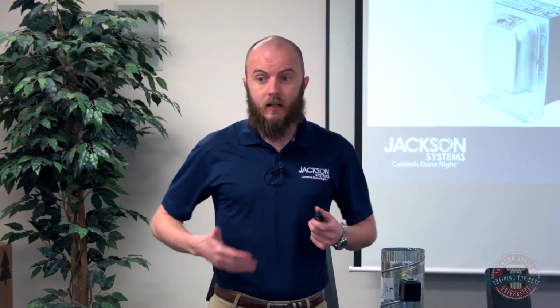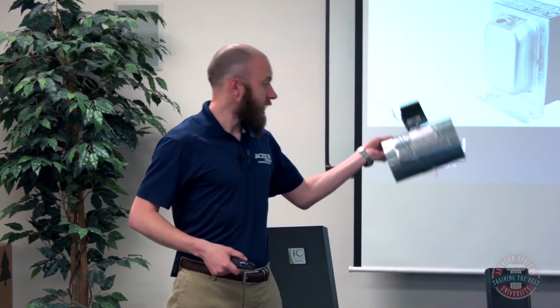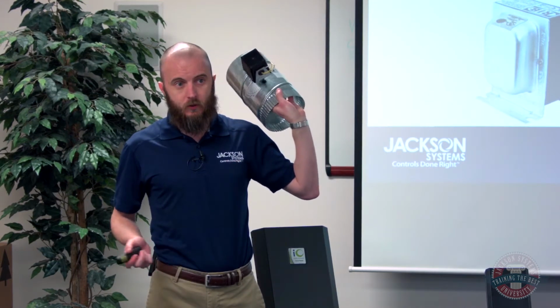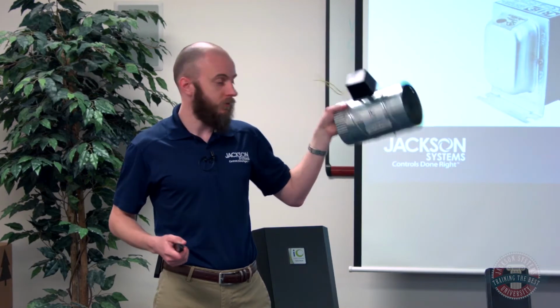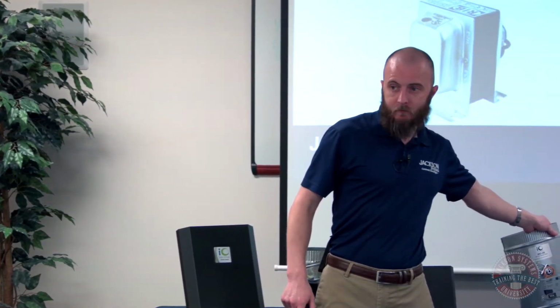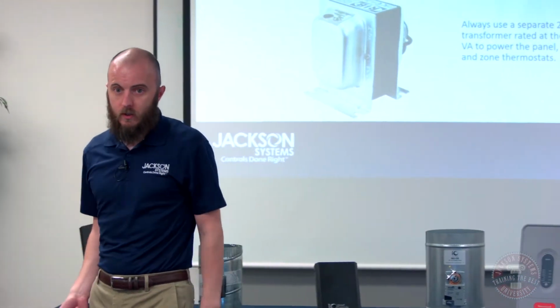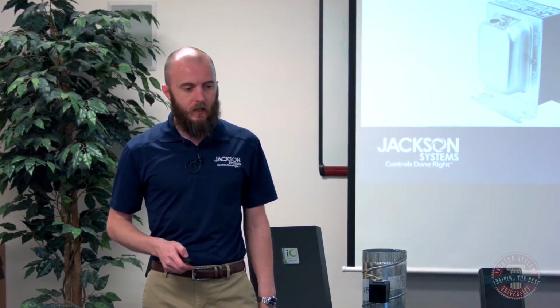Dampers can vary quite a bit in terms of their rating. So standard 2-wire dampers, these IO 2-wire dampers here, pull 10 VA each. So if you're only using a 40 VA transformer, you put 4 of these on a zone system, you're tapped out. 3-wire dampers with the Belimo actuators only pull 2.5 VA each. Those are a lot more efficient in terms of their electricity usage. You can put a lot more of those on a system or on the same transformer before you run out of juice. So keep an eye on that when you're planning it out.